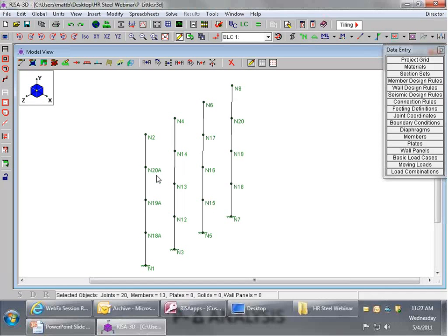And as for the amount of difference, well, it depends on your structure. Now, the 13th edition makes a big point to say, hey, you need to consider both P large and P small delta in all of your analyses. And this is true. In order to get the maximum level of accuracy, you certainly have to. But what you'll probably find in practice is that most realistic building structures, and even other types of structures as well, the columns are stout enough that they don't have a significant amount of curvature or bowing that's occurring in them, even in the case of things like cantilevered columns and moment frames. So as a result, the P small delta effect can be considered nearly negligible.